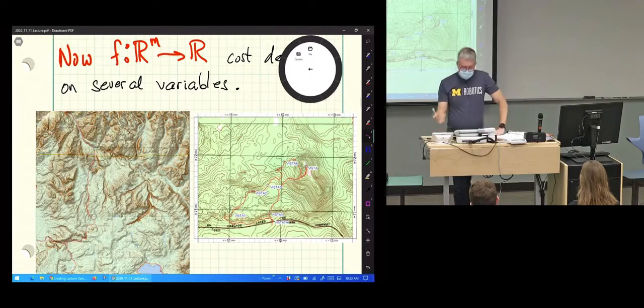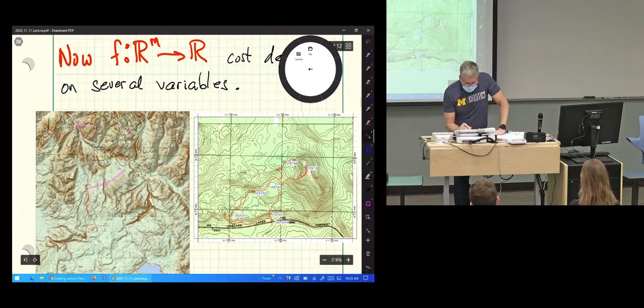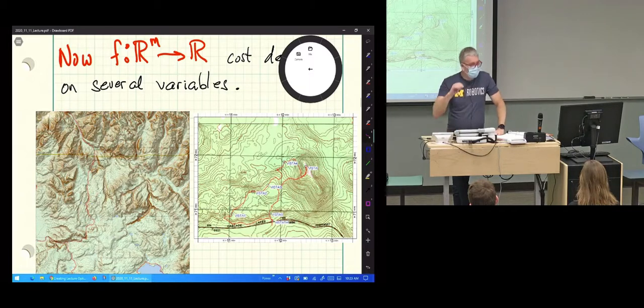If you pull out your topo map, typically it doesn't have the 3D relief that's shown over here. What you have is all these lines of constant height. Each line is, say, 50 meters difference in height, okay? So there's a fixed amount of difference when they draw the line. So when the lines are really close together, what does that physically mean to you?